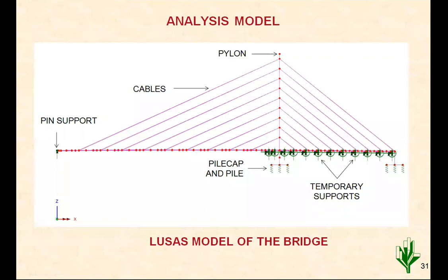Nowadays, commercially available software like Lusas, Midas has this capability of modeling stage by stage construction, and using that, all the stages are minutely modeled and the behavior of the structure during construction is studied. Whatever loads are coming there has to be precisely estimated during the initial stage itself, because any addition in the load will be multiplied by, say, that cantilever length.